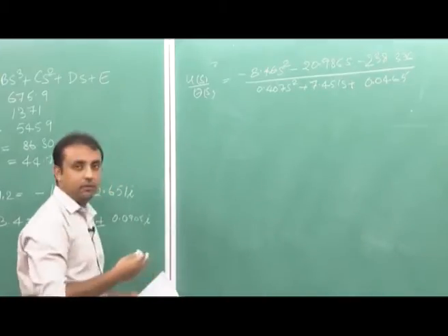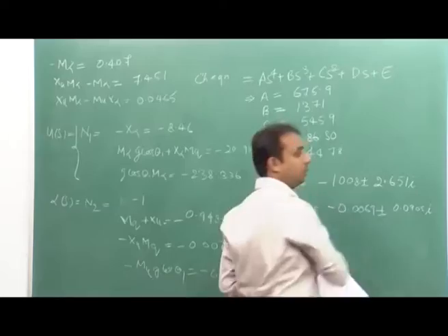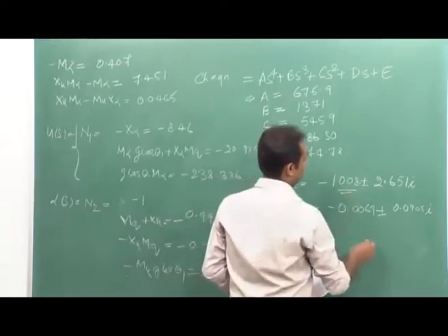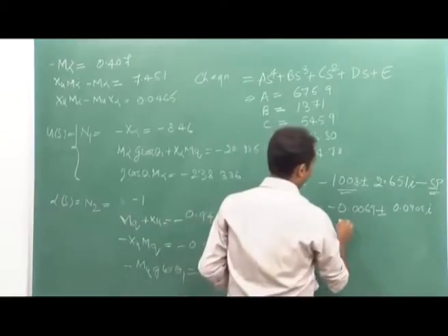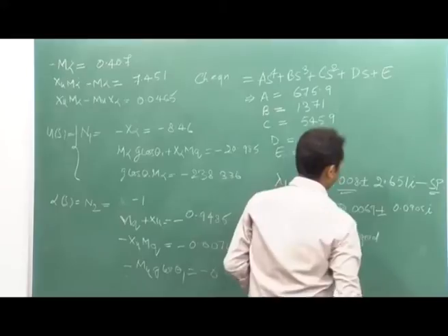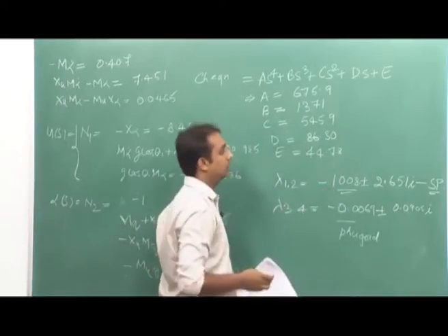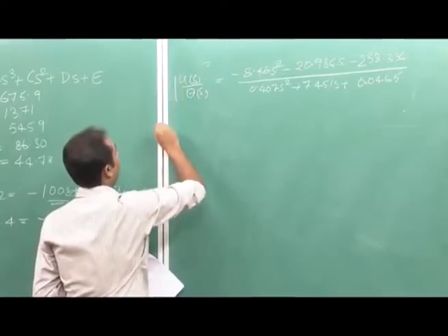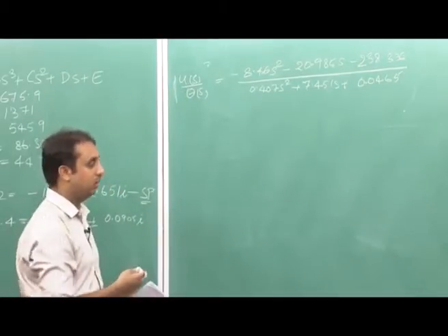Now, substituting the value of s, that is the roots of this characteristic equation. As you know, this will correspond to your short period mode roots, and this will correspond to your phugoid mode. So, let us substitute the value of the short period mode in my equation for deriving what will be the magnitude and phase of u of s upon theta of s.